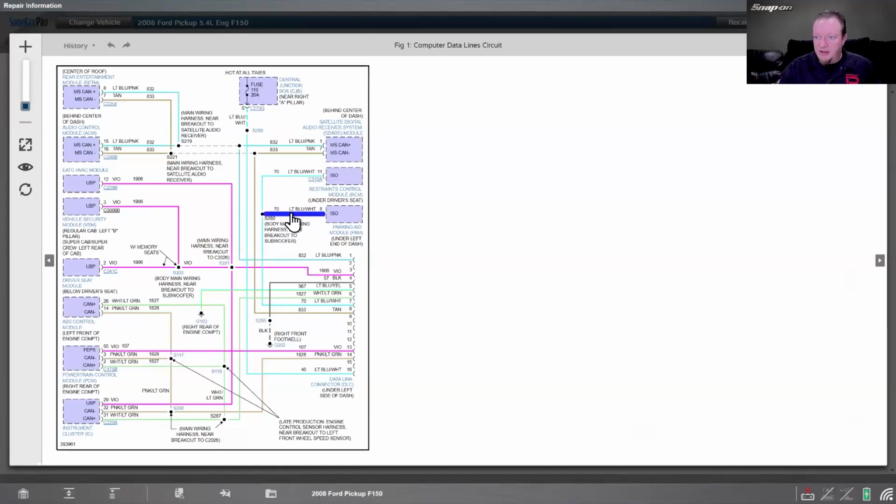So it seems like, interestingly enough, the power wire and this ISO wire, those two are light blue with white. So it's either power or it's communication line. So interesting. And you notice we also have these junctions here. They have joints. So these could fail feasibly as well.